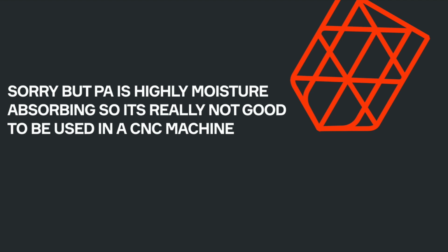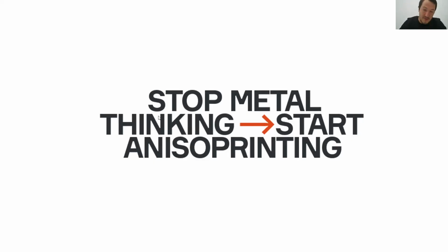Yeah, thank you for your comments. We really appreciate it, and thank you for your kind words. Then, as I mentioned, both materials, the smooth PA and the CFC PA, are based on a PA12 material. So that's one of a few PA grades that actually has a very low moisture absorption, less than 0.5% equilibrium moisture absorption.